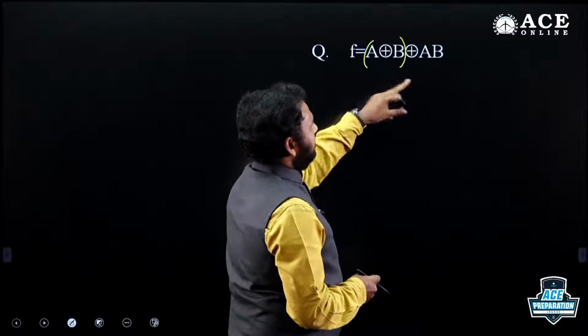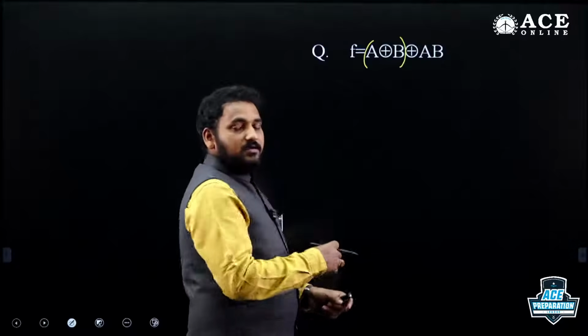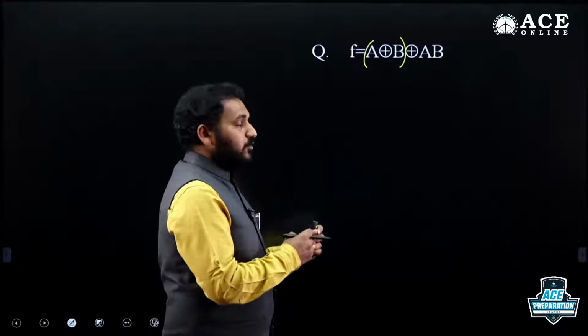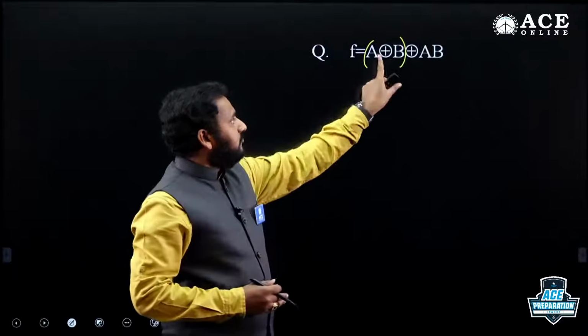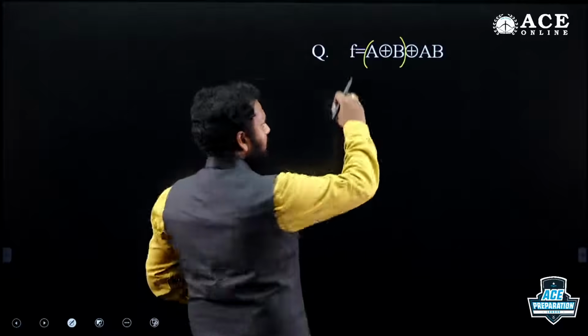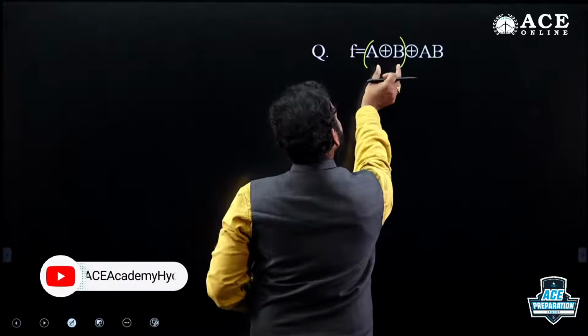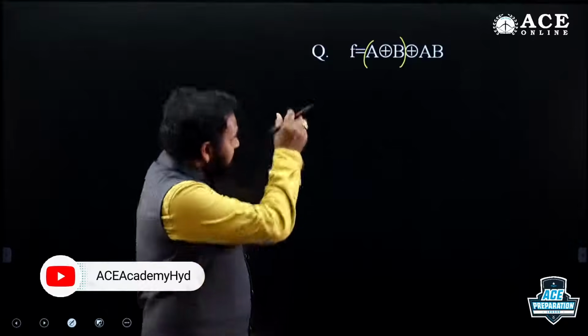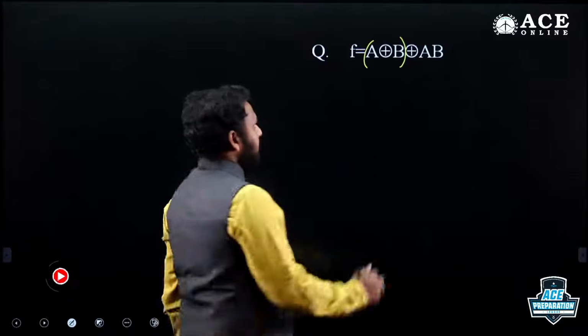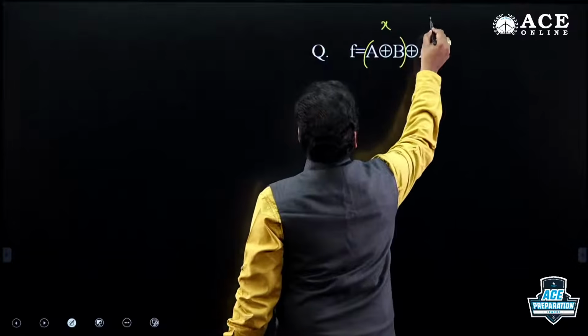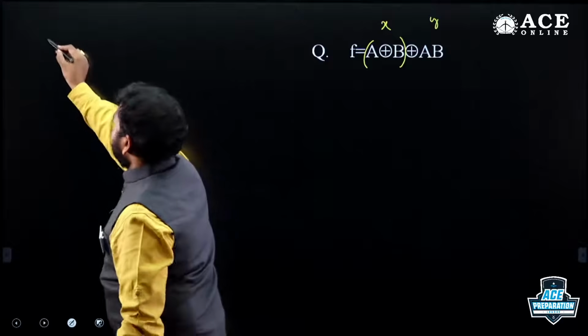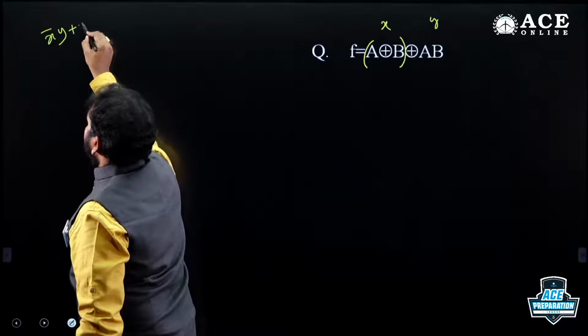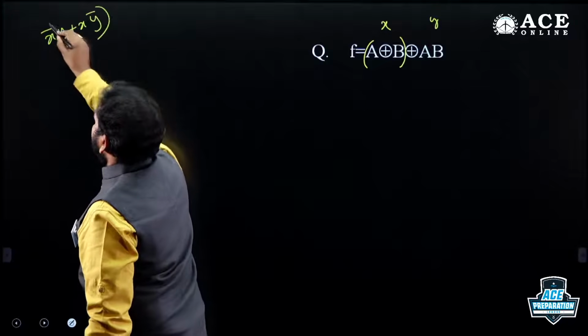It is an XOR operation, so we can separate it. Actually, these fundamentals will be covered in Boolean algebra. If you know the commutative law and associative law, you can understand how we can separate this. Just follow A XOR B; we can separate it as per our comfort. We can select any two variables, no problem in XOR and XNOR operations in the equations, right? So, I am assuming this as X and this as Y, simple. X XOR Y is X bar Y plus X Y bar, that's all.